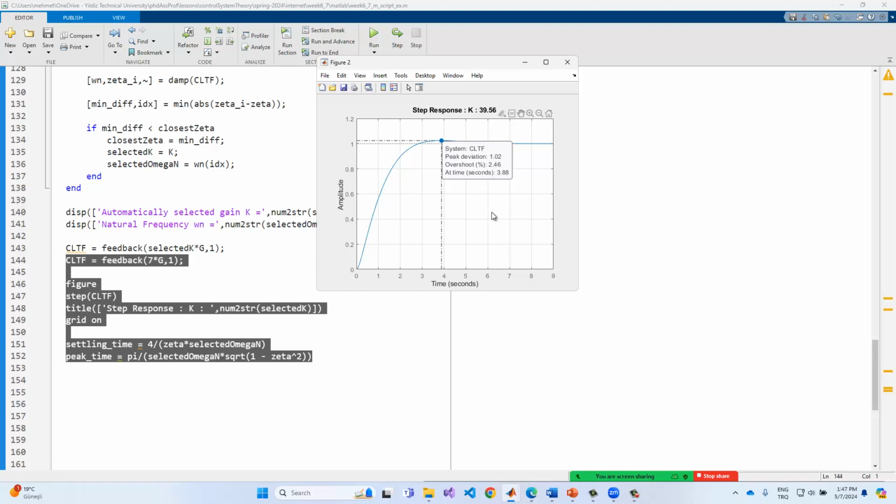So we must understand that if we have the higher than the second order system, you must assign your system with some additional parameters based on this information, if you are only using the proportional gain. Did you understand what I'm saying, Bilge? Because it's important. If you have the more than second order system, we can use still the second order approach, but we cannot match easily these two responses in the closed loop one. Okay?